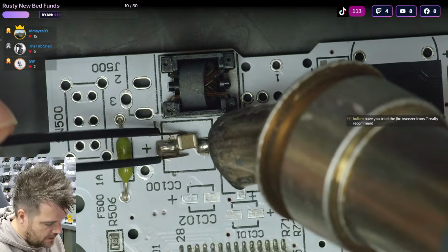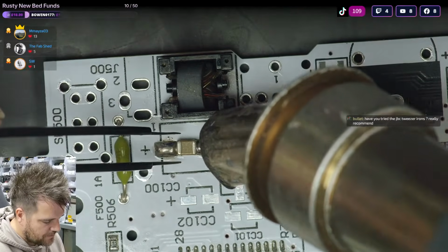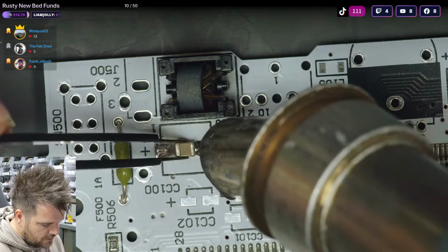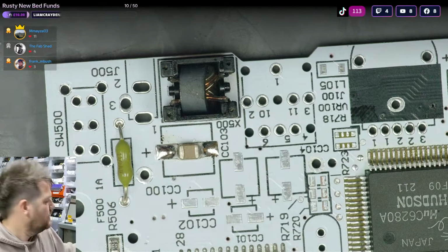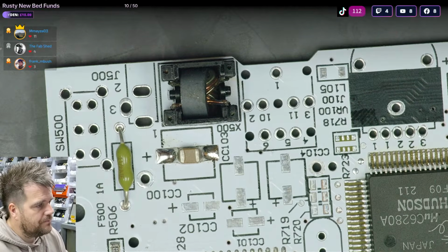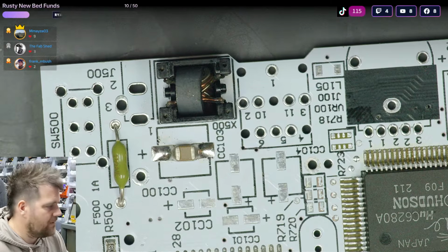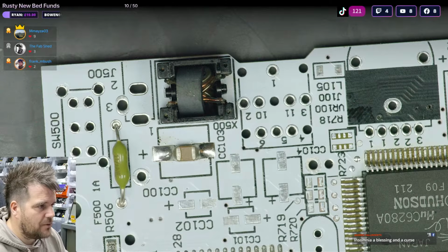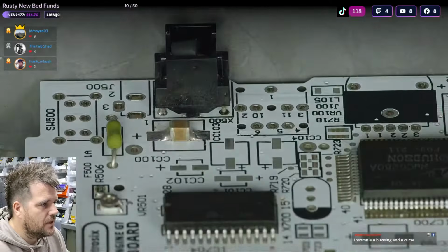Tweezer irons, yeah, I used to have them at the start. It's one of them things where I think you feel it's beneficial and it'll make jobs easier. Like I think at the start when you're trying to learn the soldering, you look for tools to help your job, but personally I don't think it's worth the desk space and the time to switch between irons. If I had a nice setup and a proper JBC with the dual setup that's nice and quick, I'd probably use them just for like whipping off caps and things, but it looks quite nice.